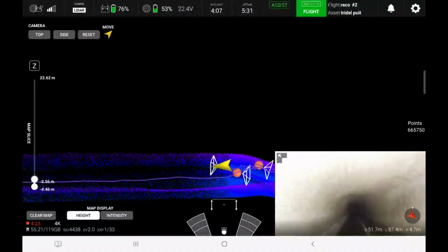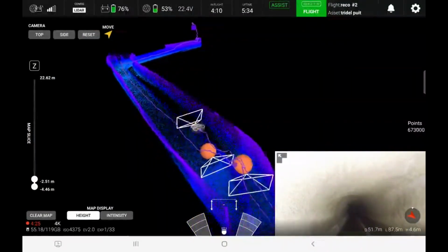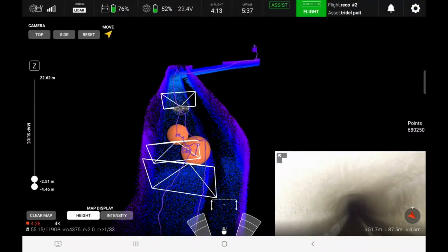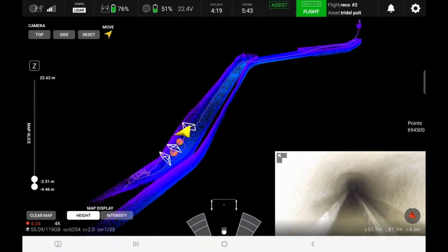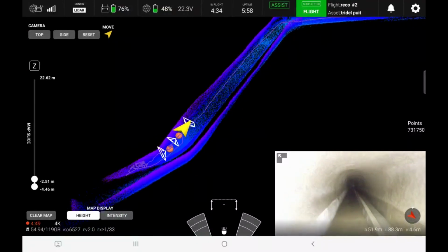He's changing with the live map view. So in here you can see that the arrow is the drone. If you zoom enough, you see the drone exactly and where the drone is aiming at the camera. So tilting up, tilting down. You can use the map to really move around to make sure you understand where is the way back. You can see the trajectory. And you also have the two red dots behind the drone, which are the points of interest that the pilot took during the flight. Points of interest are useful when you see something good, something bad, some point of inspection. We like to take points of interest during the flight. That will help us to create the report after.